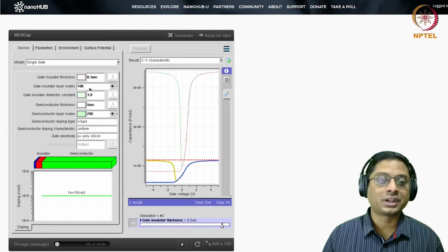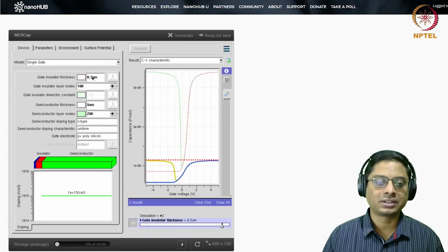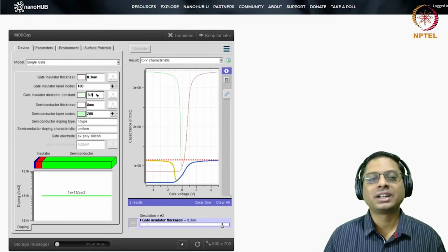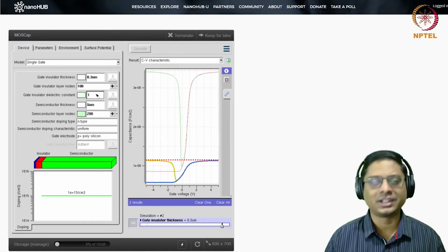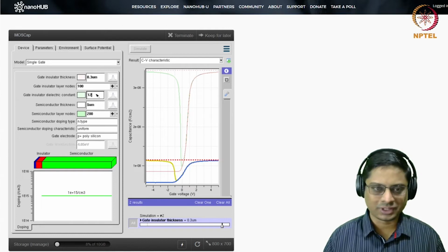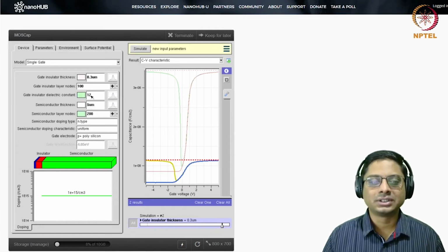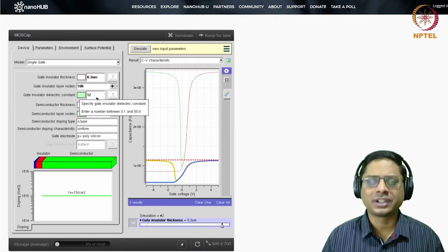You could also try, what happens if I change my dielectric constant? I'll stay at 0.3 micron, but I'll increase my dielectric constant, let's say 3 times. I'll make it 12, just arbitrarily. There are definitely some materials which will have dielectric constant of 12. By the way, you might ask, you said that dielectric constant of hafnium dioxide was 25, right?